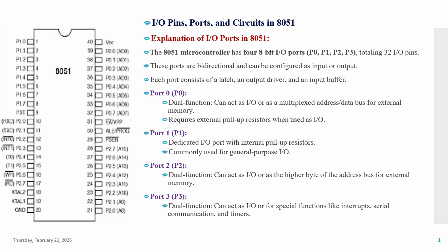Port 2 is also a dual functionality port and acts as an input-output port. It serves as the higher byte of the address bus for external memory. The last one is Port 3, P3. It also has dual functionality, acts as an input-output port, and supports special functions such as interrupts, serial communication and timers.